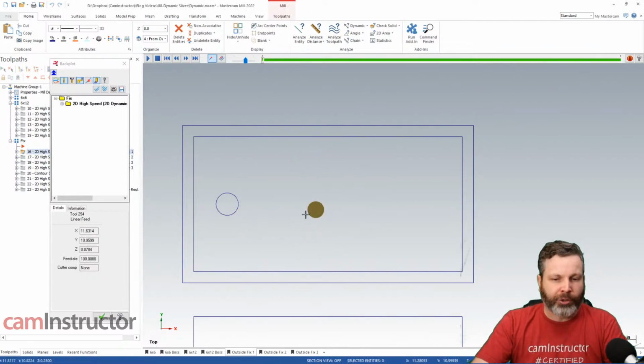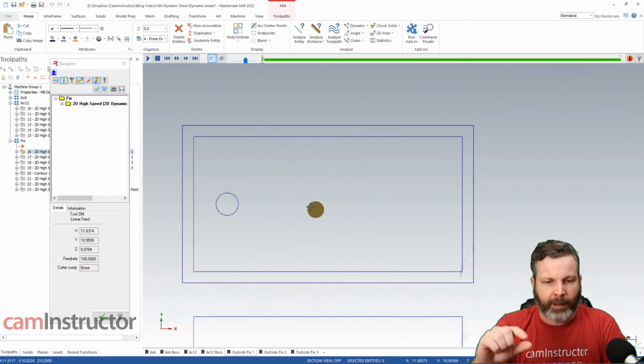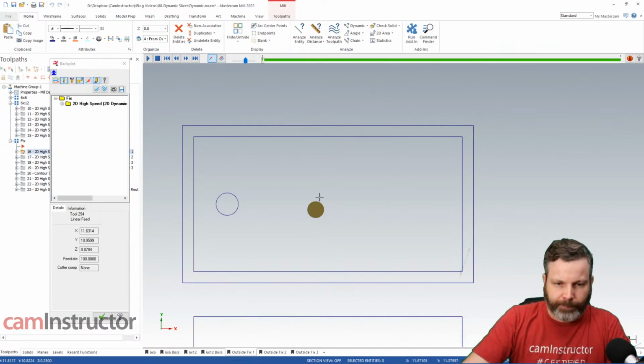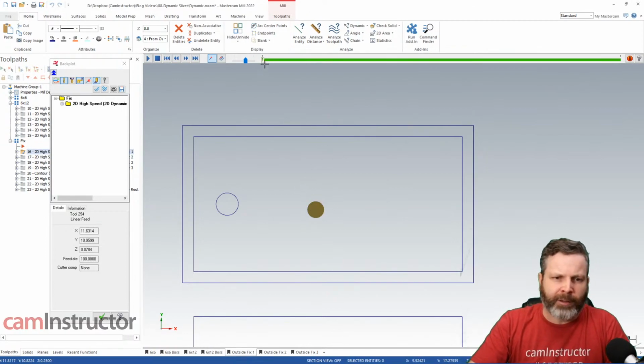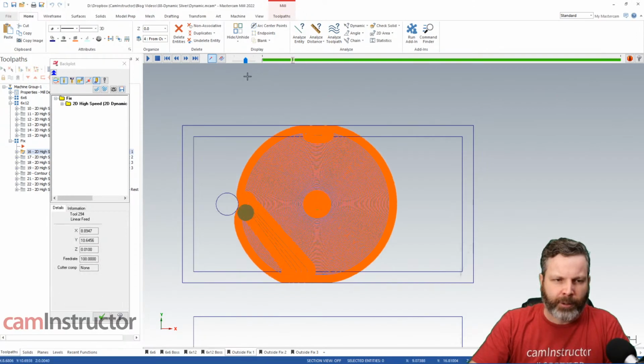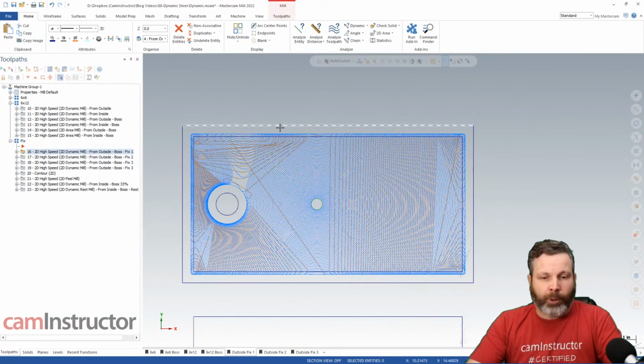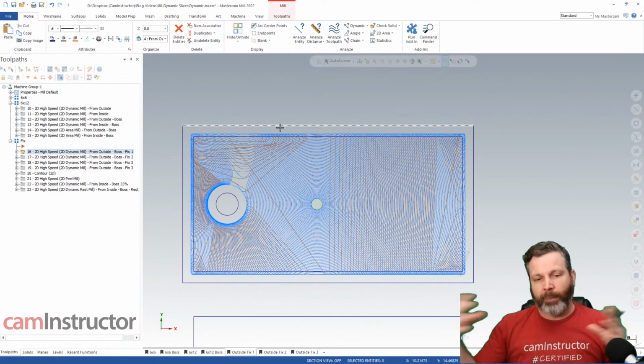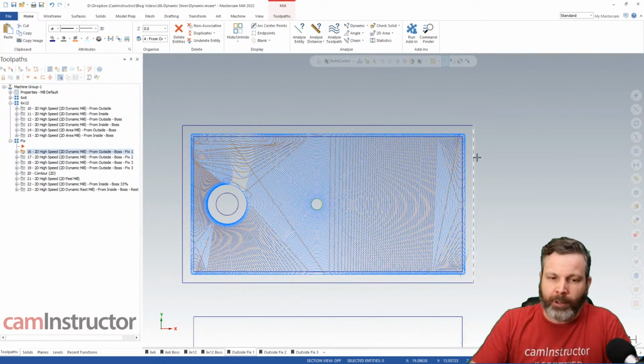But you could drill a hole here. You could drill a hole that's maybe 10 thou shy of your floor, and then you're only helixing into 10 thou of material, and that would definitely work. So that's possibility number 1. Switch the strategy to from inside, draw a bigger boundary, and cut it like that. What's another option, what we can do here?